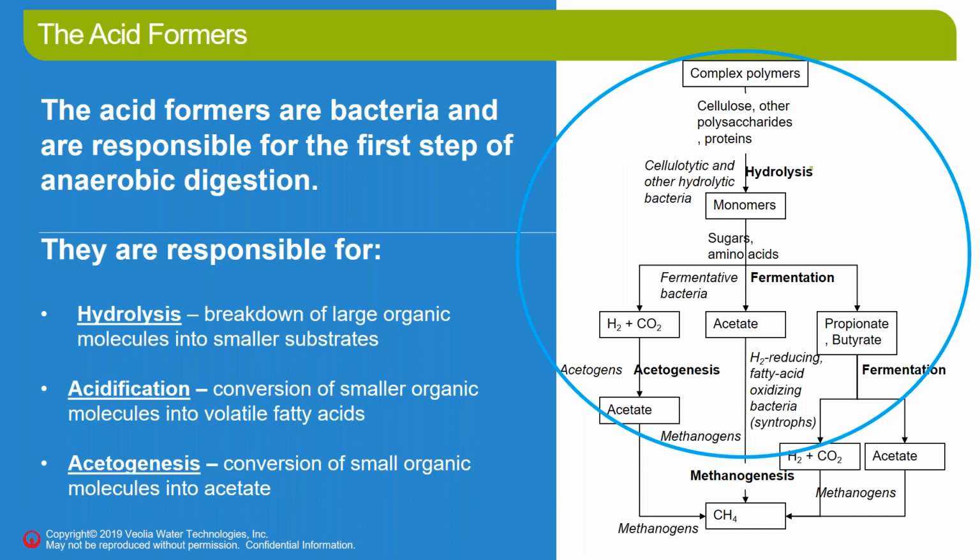Or think of that hydrolysis in a solids digester: it would start to break down large pieces of biodegradable material. They start to break down the leaves. They start to break down the pieces of meat. They start to break down starches or pieces of rice or pieces of food. Anything like that, any biodegradable solid. Hydrolysis is starting to break those down into smaller molecules that can be dissolved in water.